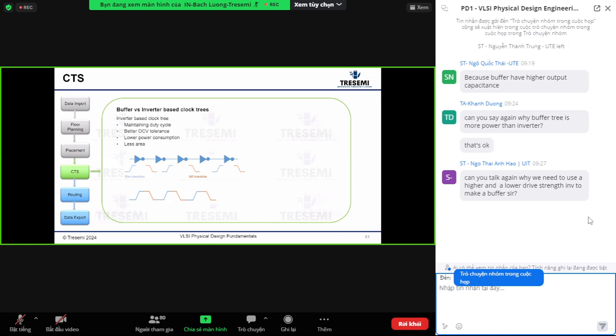So you might want to change that to inverters, then it'll use the inverter tree. You can play with it. Tell it to use the buffers only, and then the inverters only, and you'll see the number of inverters versus the number of buffers it added. Inverters should be a lot less.